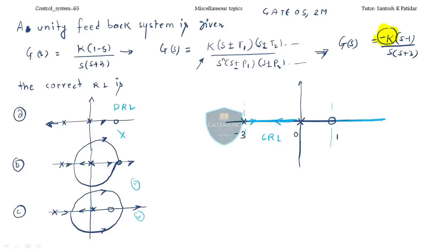Now we'll find if two poles are meeting. If these two poles are coming like this, definitely you will have the breakpoint for this question, isn't it? When you find the breakpoint, you know very well how to find the breakaway point. So the breakaway points for this question you will get are 3 and -1. So 3 is not a valid point. Here at 3 we do not have two poles meeting, so we do not have the breakaway point there. So the breakaway point will be at -1. Yes, we can have it here.